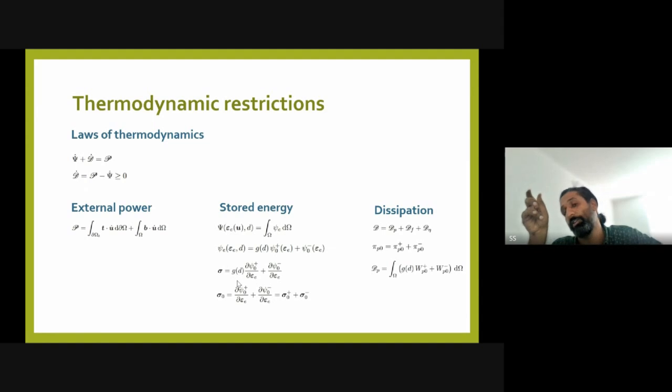to the artificial viscosity. So here we have decomposed the effective stress in the plastic dissipation into two parts, which is basically a scalar measure of the stress. Sigma naught was a tensorial measure of stress, but to write the plastic dissipation, we usually prefer a scalar fashion so that we can relate it with the accumulated plastic strain, which is a scalar measure of the plastic strain that we are going to take. In that way, we can write the dissipation due to the plastic flow in the material as dP.